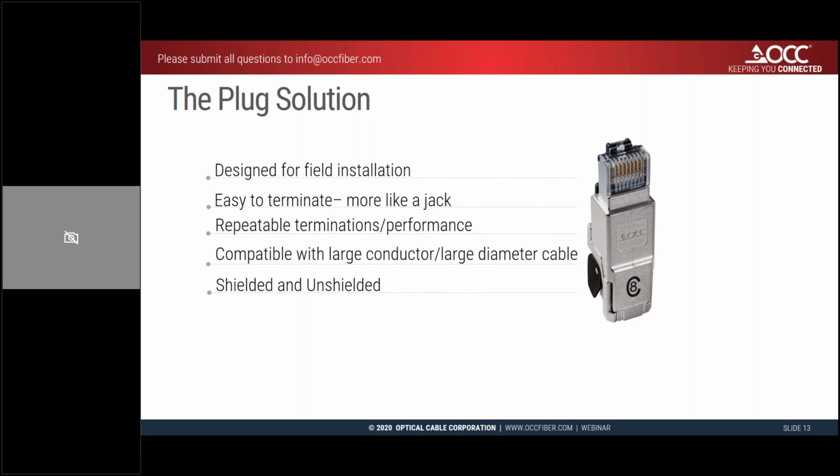Okay, the solution for all that would be a field terminable plug, such as this OCC field terminable plug. These are designed for field installation. They are easy to terminate. They terminate a lot like a jack. You can get repeatable terminations and performance out of them because inside this thing is a printed circuit board, which doesn't change. And they are compatible with the larger conductors and the larger cable diameters that you'll see with Cat 6A and whatnot. They also come in shielded and unshielded varieties.